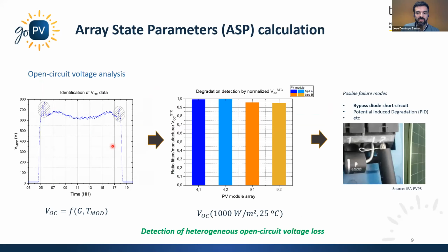One specific algorithm is devoted to the identification of the time when the maximum power point corresponds to open circuit voltage. From the later analysis of the open circuit voltage data at different irradiance and temperature, a set of equations is obtained which can be used to produce the VOC.